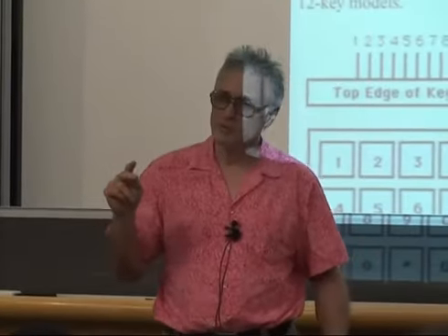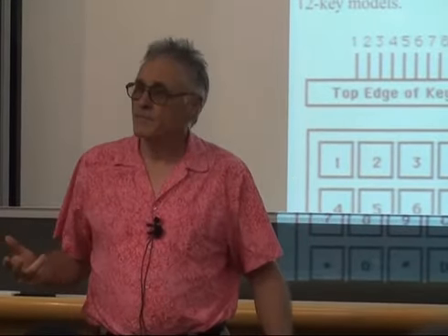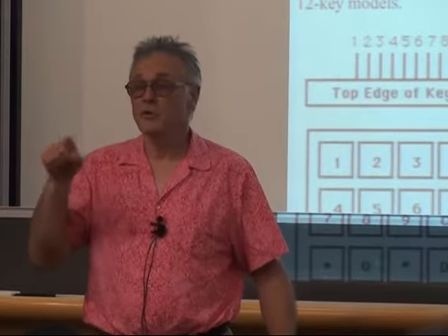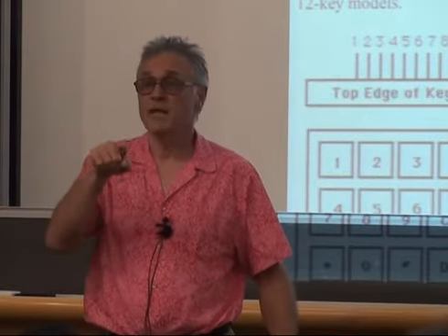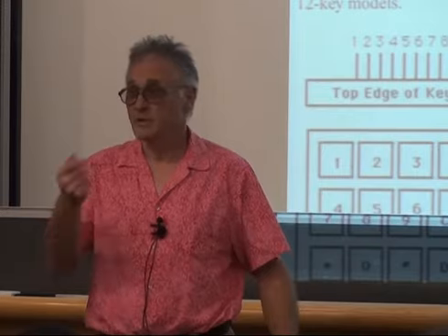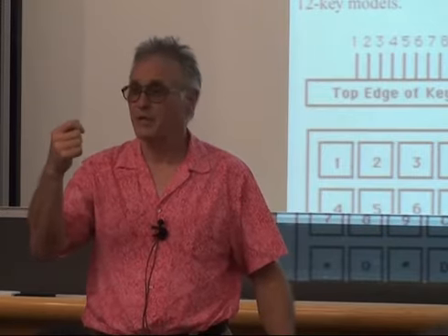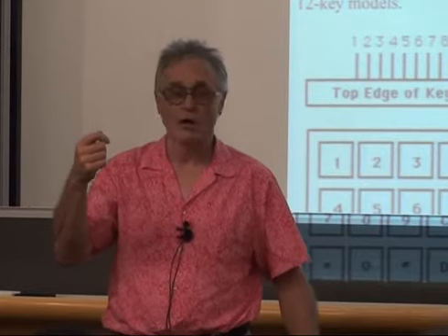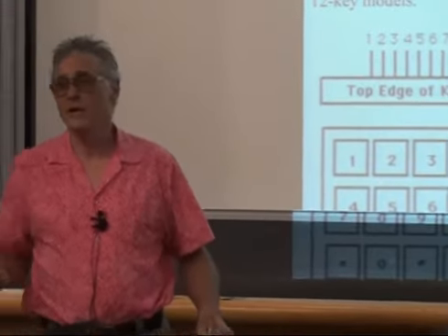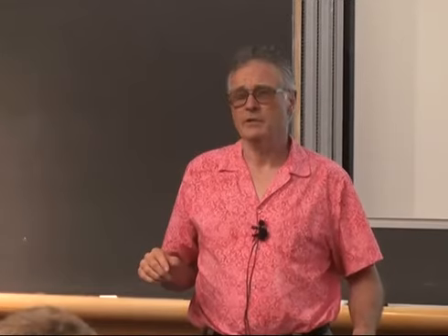There's usually 2 numbers printed on a capacitor. One is like 203. 203 means 20 times 10 to the third picofarads. So it's 20,000 picofarads, which is 20 nanofarads. And someplace else will be the chemistry or the dielectric of the capacitor, and it will say something like X7R on it, which is a very inexpensive but fast dielectric. Watch out for dielectric absorption.